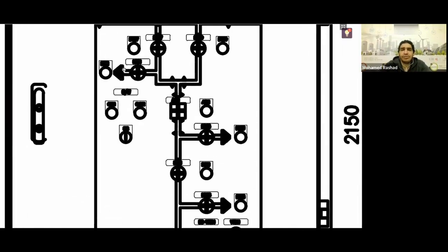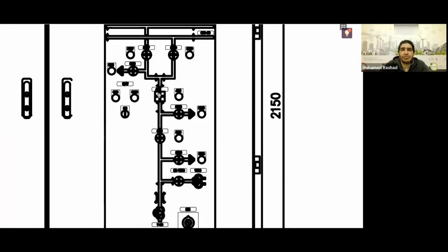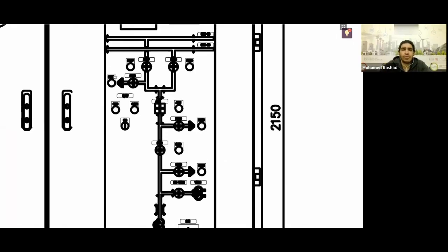All right, engineer, you see the circuit breaker here, and here are the switches, and here is the ground, and so on. Next to everything, you see a push button next to it. This is called select. And here you have two general push buttons, one for close and one for open. If you press close, which of these components will close? It will close the one you have selected.